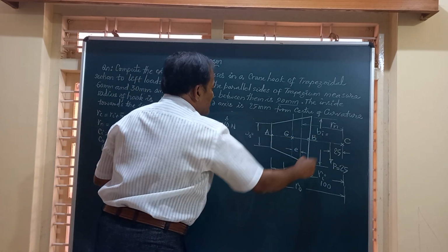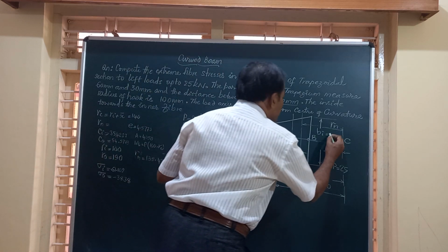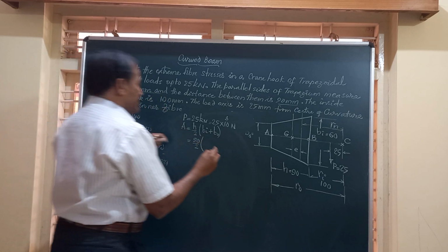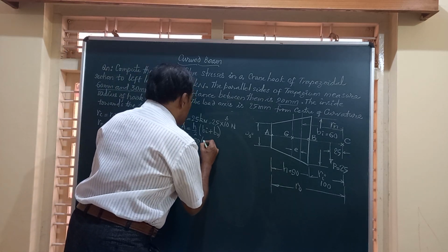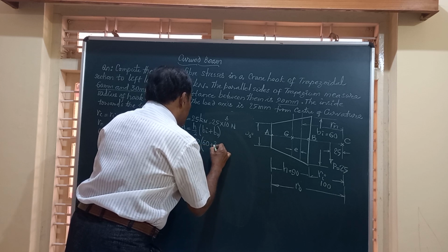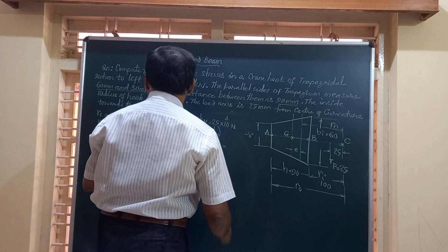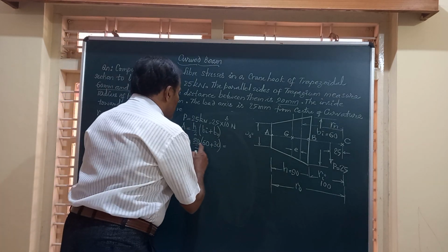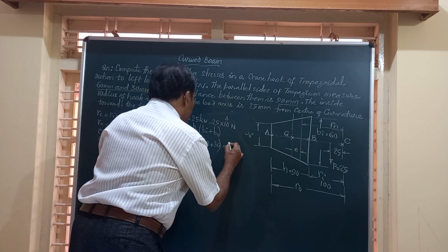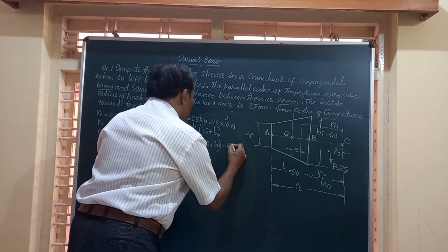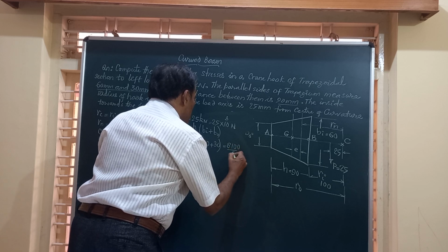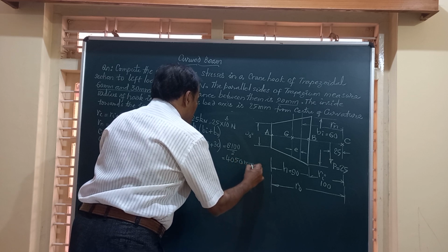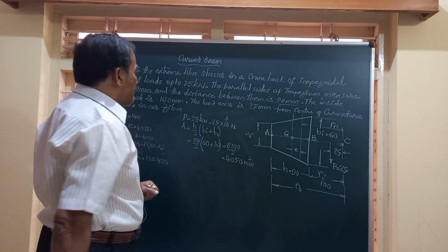Bi is this value, that is 60, given in the question. You can just see here 60 mm and 30 mm are the sides. So Bi is 60, B naught is 30, and friends, if you simplify, this works out to the area. Let's find out. This is 90 into 90, 8100 divided by 2. This is 4050, 4050 mm square is the value of this area of cross section.